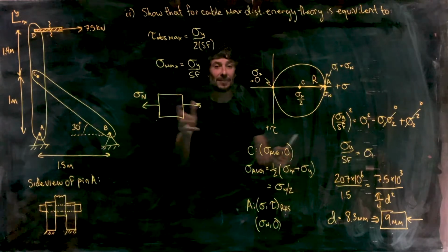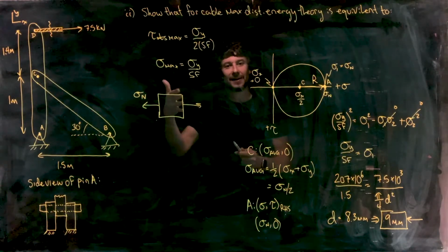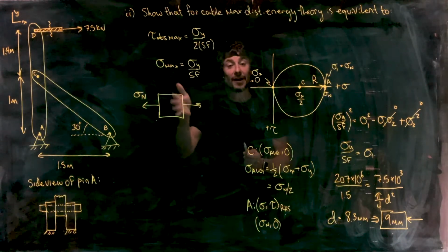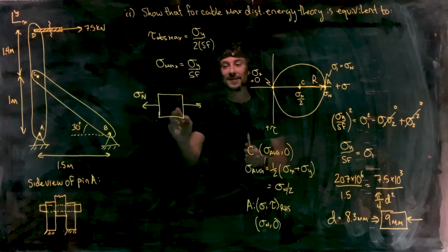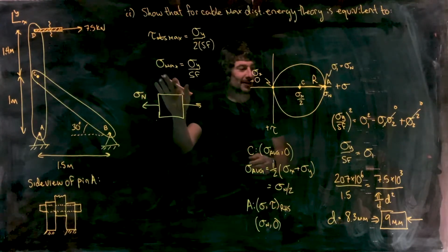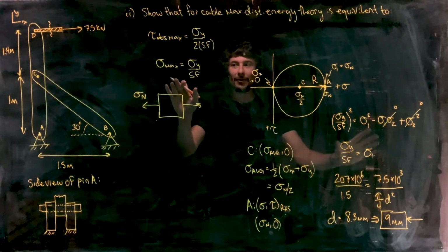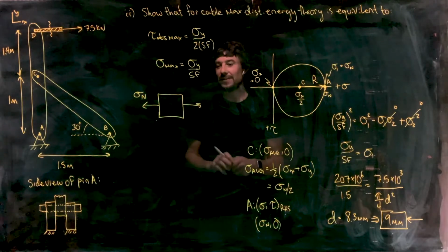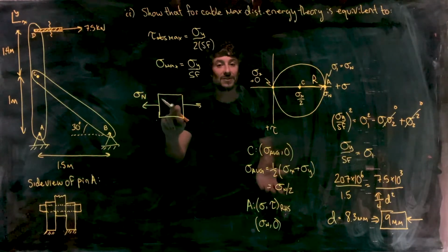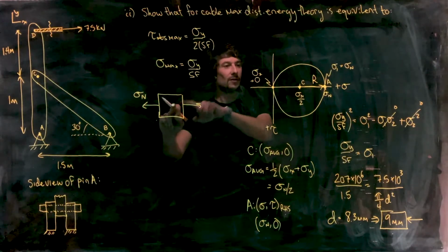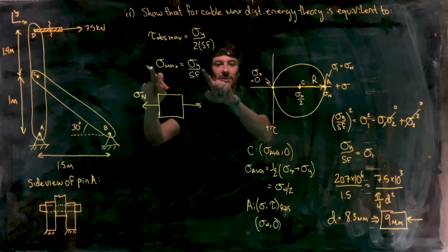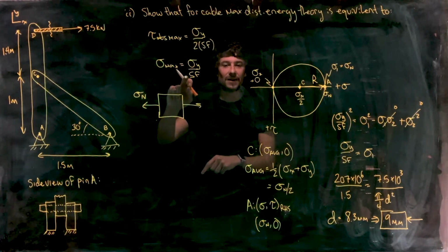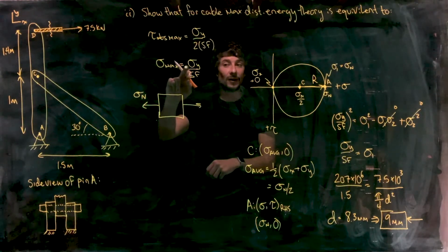And that's really interesting because it means that what you were doing back in lecture 2 and lecture 3, it's all still okay. You weren't doing anything wrong back then. The problems were designed so that they were all uniaxial stress. So knowing the failure theory now, or knowing about the failure theories, wouldn't actually change what your answer is for those problems. So what this really tells you is that if you come across a problem that's uniaxial normal stress, then you don't need to go through the process of drawing Mohr's circle and applying the failure theory. You can just use your simple form of failure analysis, which is maximum stress equals yield stress divided by safety factor, or if you're dealing with brittle materials, the ultimate strength divided by safety factor.